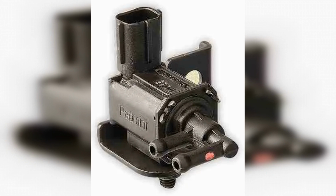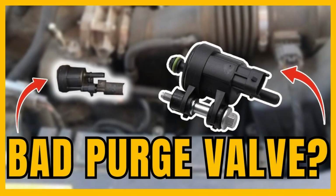In conclusion, understanding fault code P0496 is essential for maintaining your vehicle's performance and emissions control. A high purge flow in the canister purge system can lead to various issues, including decreased fuel efficiency and increased emissions. By diagnosing the problem accurately and addressing it promptly, whether through inspecting the purge valve, checking for leaks, or ensuring proper electrical connections, you can help ensure your vehicle runs smoothly and efficiently. Remember, regular maintenance and timely repairs are key to keeping your car in top condition.